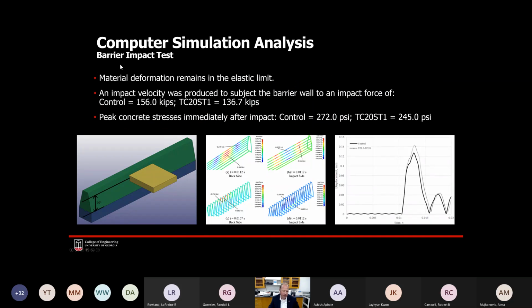Once we finished that earlier phase, we actually ran the next two things I'm going to talk to you about in parallel. One of the things that we did was develop a finite element model. That phase of the study initially involved evaluating a material model that was most appropriate for our fiber reinforced rubberized concrete material. So we did play around with some different material models that were out there. Once we took those models, we compared them against some of the experimental data that we had and found one that we feel very confident with.